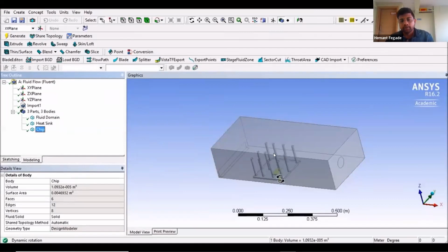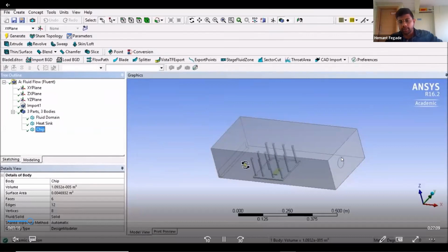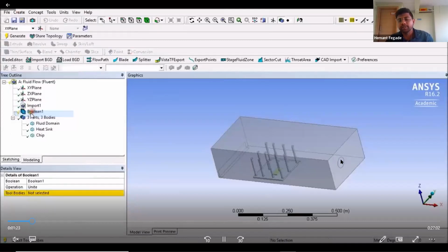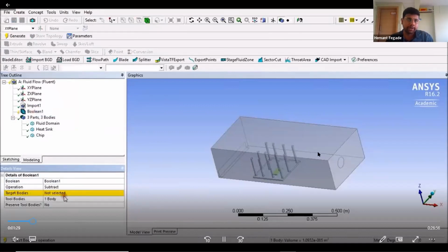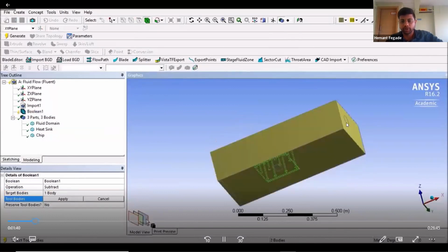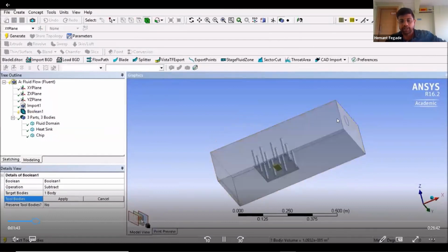And here you can see a small circular section has been made over here. This is going to be the actual inlet through which the air is going to go over. So instead of a fan, we can also simplify the simulation further by excluding the moving parts, where we can consider that air is simply moving over this heat sink, and it is coming from this particular hole or circle, moving forward.